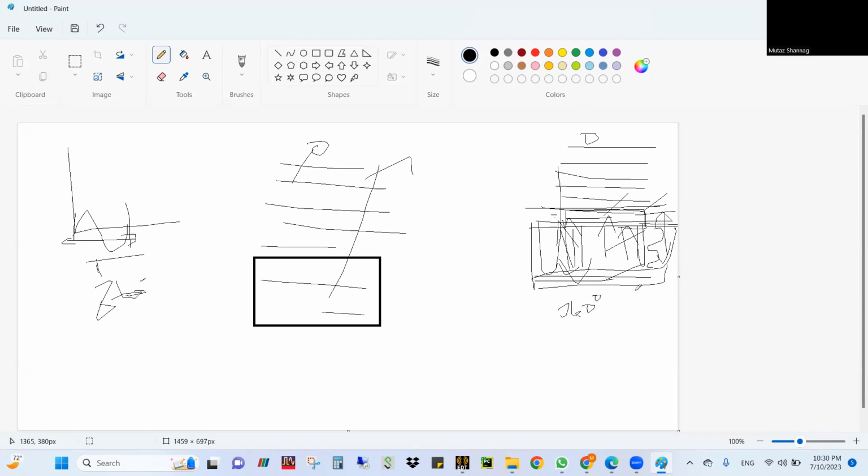But that holds good for free space, basically. Here it is not free space, it is a dielectric, which has a value of 2.1 or whatever it may be. So it will have a further delay, because why? Because you have lambda g, the guided wavelength, which is lambda naught divided by the square root of epsilon r. So whenever the dielectric constant changes, your guided wavelength will change, right? Accordingly, the phase also gets changed, basically. That's how you will experience the phase.